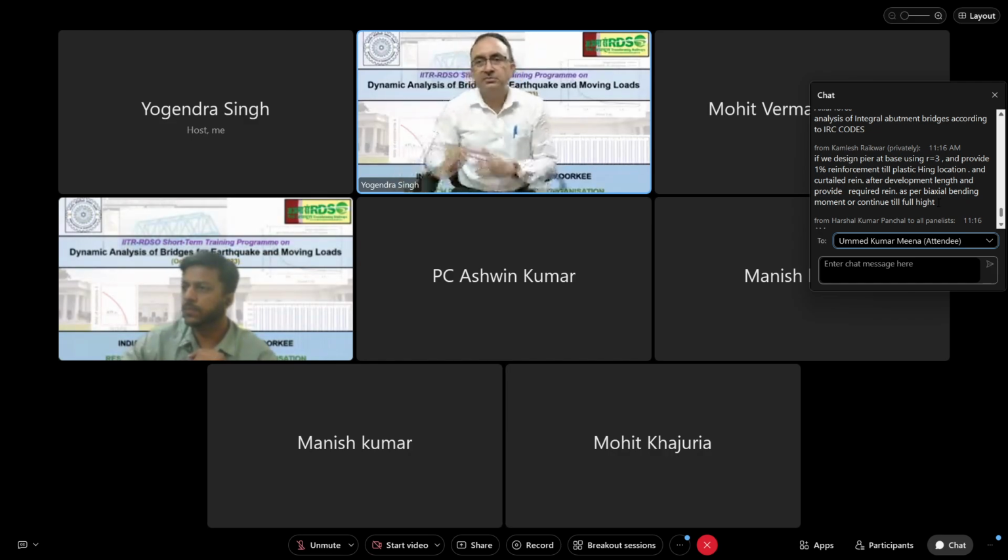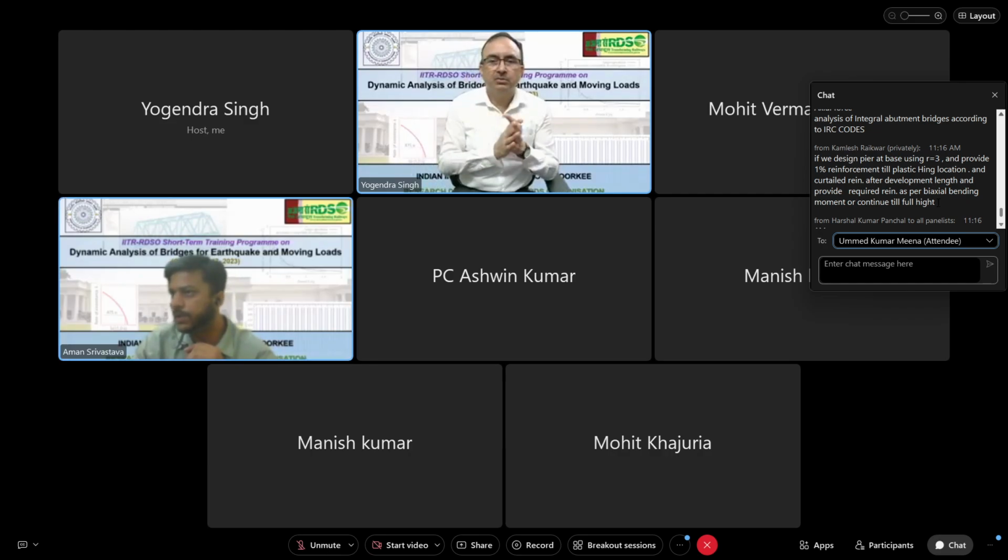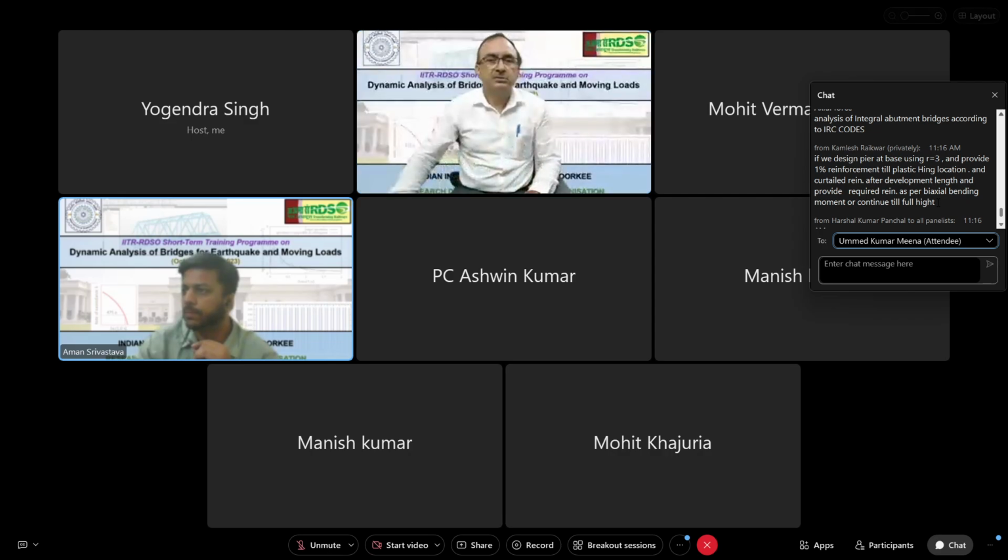Okay, sir. The question is from Kamlesh. If we design pier at base using R is equal to 3 and provide 1% reinforcement till plastic hinge location and curtail reinforcement after development length and provide the required reinforcement as per biaxial bending moment, or should we continue it to the full height?